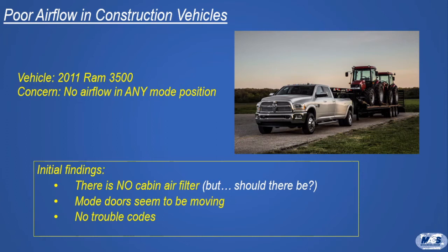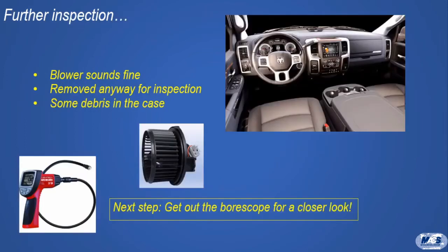The technician checked for trouble codes, and there were none. The blower sounds fine, but the technician removed it for an inspection just because that was easier than going for a dashboard removal at this point. And even if he eventually had to take it out, the blower removal would not have been wasted effort. With the blower out, he could see some debris in the HVAC case, so he decided to make a more detailed inspection using a borescope with a camera. That made the problem really apparent.